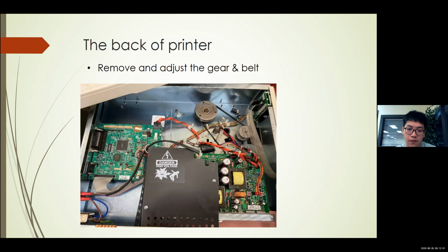The adjustment of the belt is also very important. Too loose will cause the roller to be unable to drive. Too tight, the belt will fall off after a period of operation. It seems very simple to install a recycling roller, but in fact, it is very complicated and needs more patience.